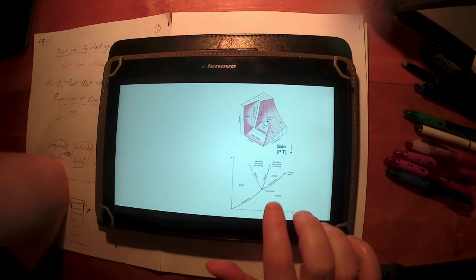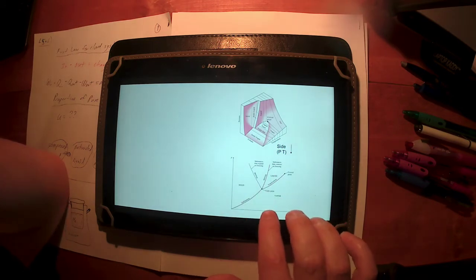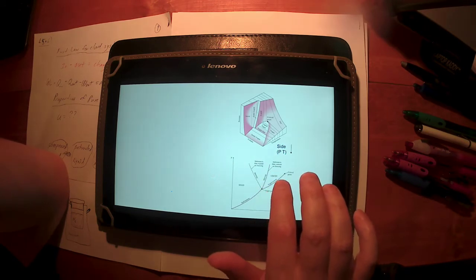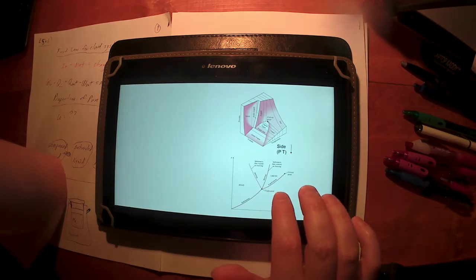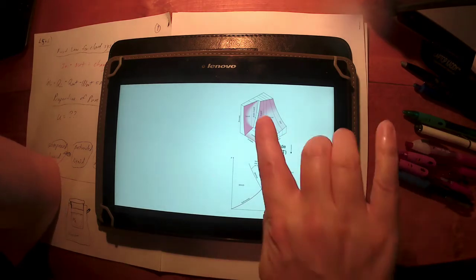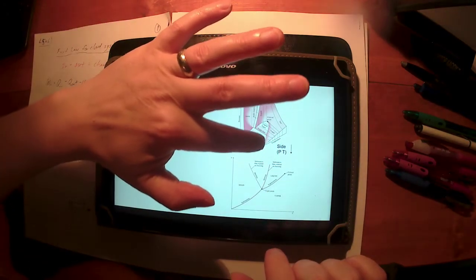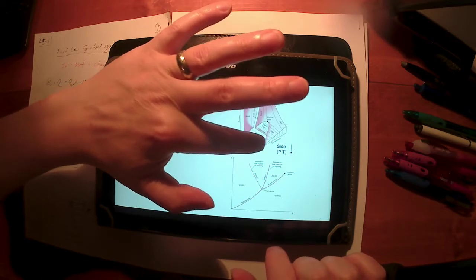Okay. Now, often the PT diagram is referred to as the phase diagram, because given a pressure and a temperature, I can just go figure out where am I in relation to the vaporization curve or the sublimation curve, depending on what I need information for. But again, if you view this right straight on, your sublimation curve right here between vapor and solid represents this bottom part of the dome region.